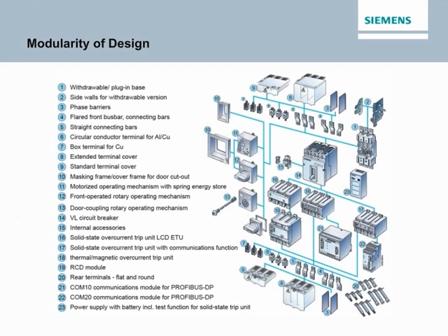Internal accessories for VL breakers are field installable and are conveniently located in pockets behind the front accessory cover. To simplify the selection of accessories, just 2 groups of internal accessories cover the entire VL family. Additional external accessories are also available to accommodate a wide variety of application requirements for connecting, mounting, and operating VL circuit breakers. Communications modules are available for connecting to Modbus or Profibus DP systems. The accompanying illustration identifies the array of trip units, options, and accessories for use with VL circuit breakers.